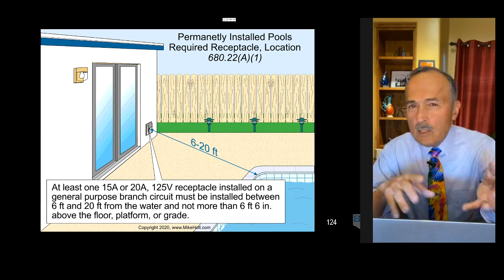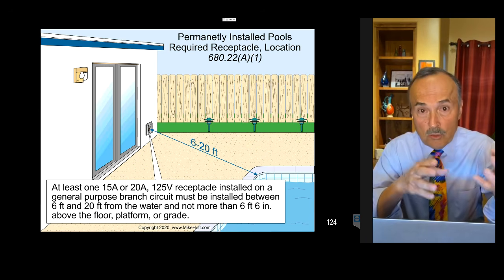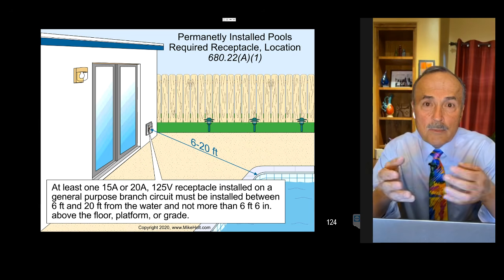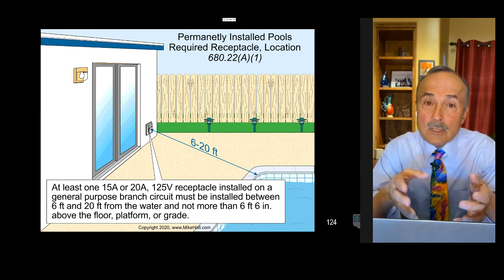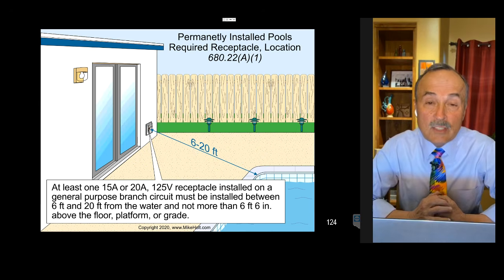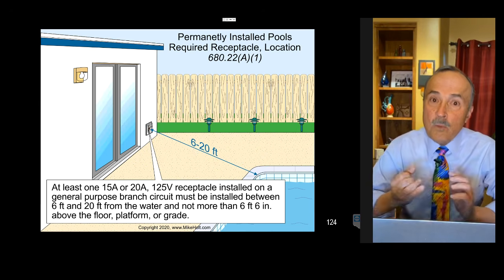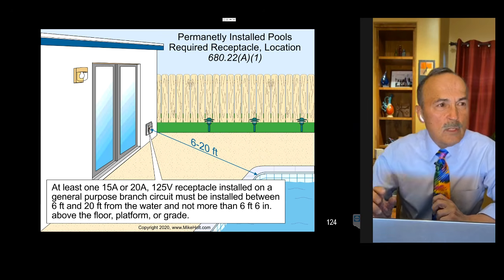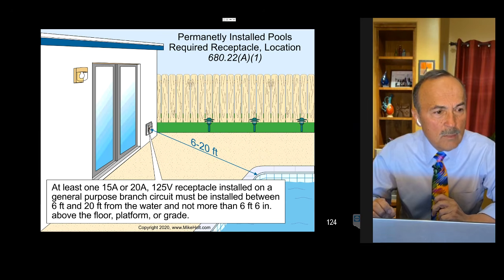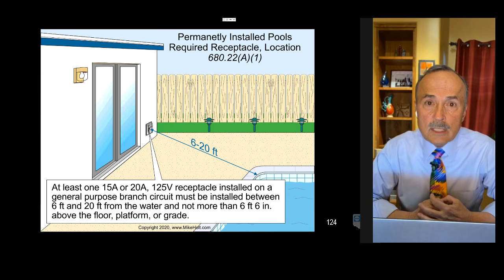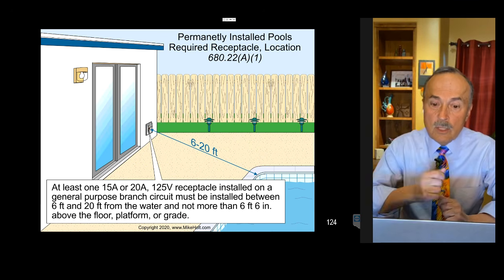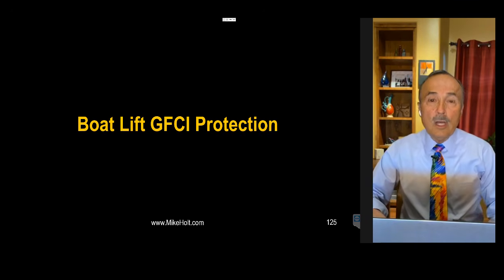So the question, I don't understand, what are all the changes? Well, all the changes is because the person was describing all the problems he has. And so therefore, a duplex receptacle has to be GFCI protected. It does not have to be a GFCI receptacle. It has to be weather resistant, tamper resistant. It's going to have the cover. What rule is the cover? Let's see. The cover would be the same rule. It's going to be 406.9. It talks about the weather resistant, talks about the type of cover, the in-use cover. And that's all I got.